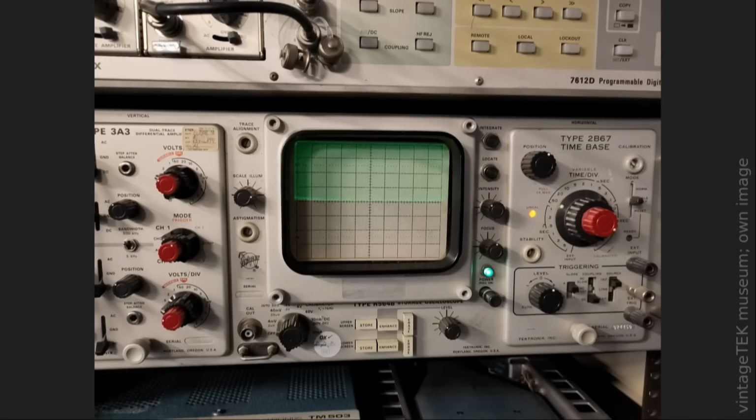In the bad old days, people tried capturing glitches with cameras pointed at oscilloscope tube displays. Or they fell back on clever indirect means of measurement and deduction. But just being able to see the glitch on the screen would be so much nicer. These days, we solve this problem with digital memory. But back in 1962, that was not an option. Tektronix's solution was to make an oscilloscope screen that remembered what you drew to it. The Model 564 here was the first scope they sold that had one.